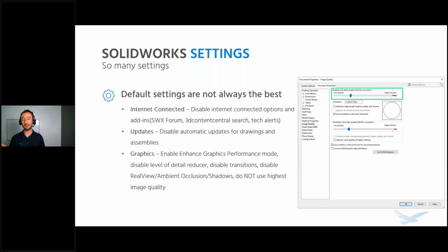And what you'll find is that if you do that, and then switch back to your assembly or your part, and just hit Control Q to do a full rebuild, you find that the rebuild, to just do the graphical rebuild, it might take much longer. So if you're seeing at the bottom left or bottom right hand corner of your screen that it says updating graphics, that might be caused by this setting being cranked too high and causing that graphic setting to just take too long.